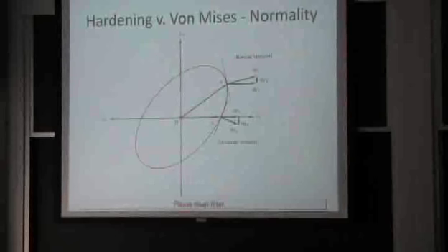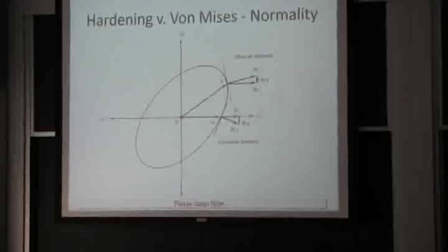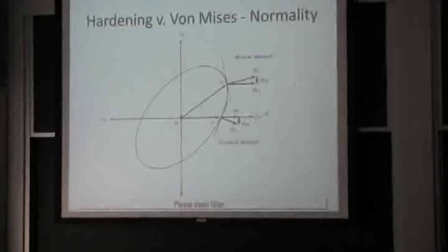It's explained a little bit in the text, and what it means, for example, for a uniaxial strain is that not only you get a strain in one direction, but you also get strain in other directions. So you have a shrinkage in a corresponding direction, and that's given to you here in this schematic. So the yield surface will grow perpendicular to itself locally.